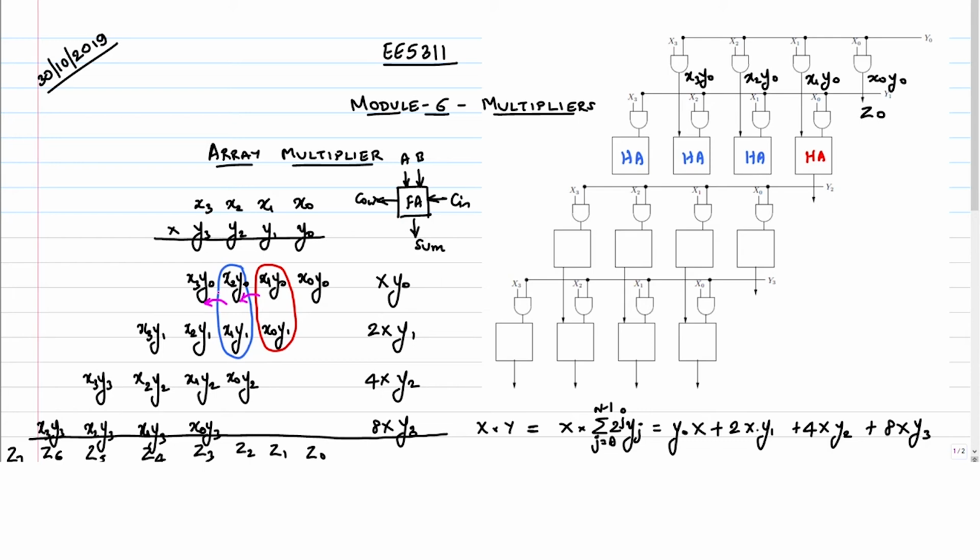So first of all, can that be a half adder at all, in the way I am showing you here? Why? Because I'm propagating the carry. Therefore, these blocks have to be full adders. Right? And I'm going to propagate my carry like this. Okay? Now, what is the output of this half adder in red? That is nothing but Z1, right? So, this is going to be my Z1.